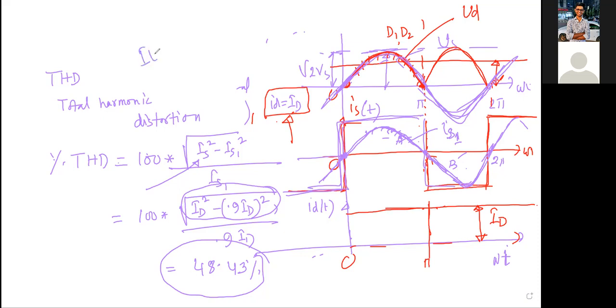So IEEE have suggested you cannot make this total harmonic distortion more than 6%. It will be within 6%. You understand what I want to say? How can you do that, sir? Yes, sir, I was also asking this. How can we actually do this? Yes, a lot of research is going on. People are using filtering, people are using some switching on the input side and some on the output side. New ideas they are proposing to reduce this total harmonic distortion.